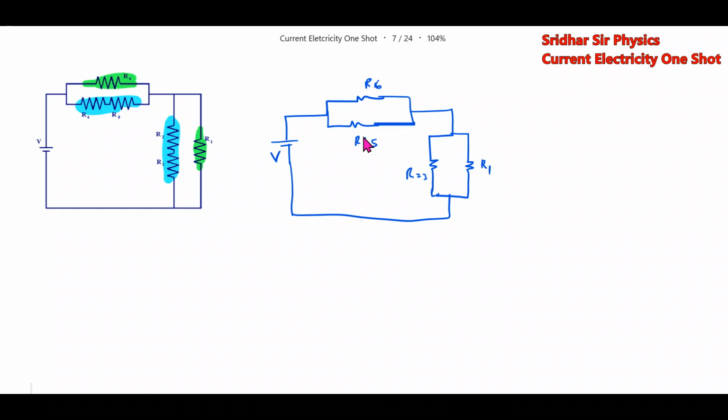So now these two are parallel, these two effective in series. So like this we should simplify. Now what about these two? These two are in parallel and that effective will be in series. Identifying series parallel is important. So if I go for current division, it will be like this. Here IA, IB, the same current, here IC and IT.